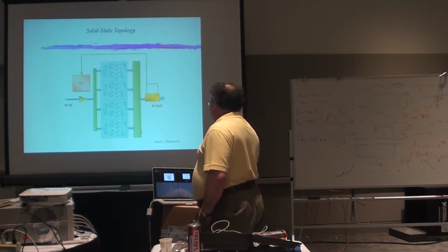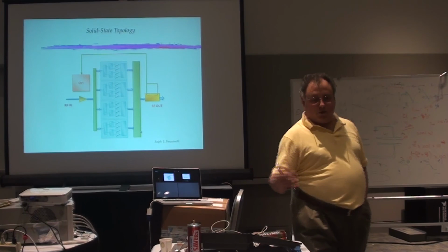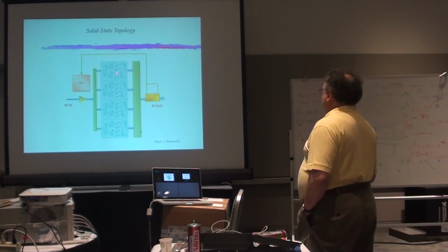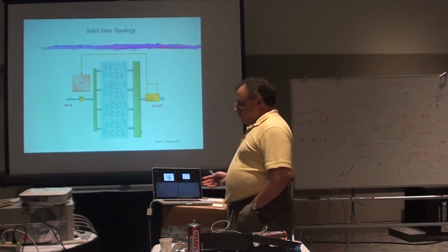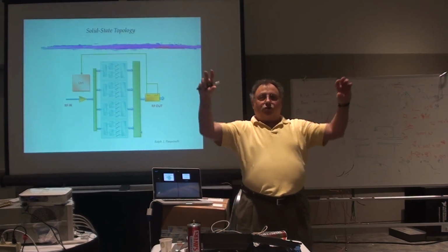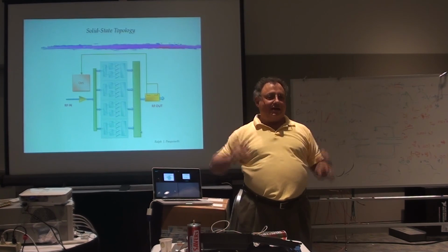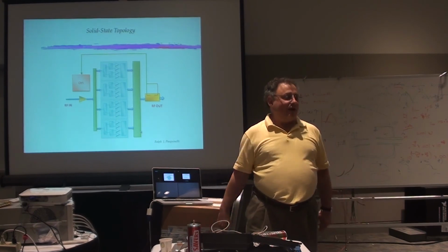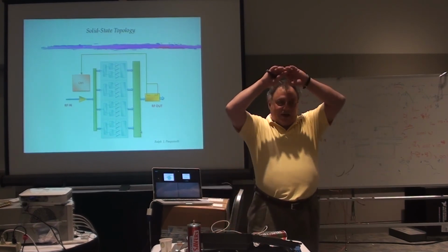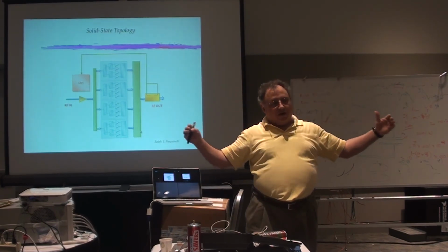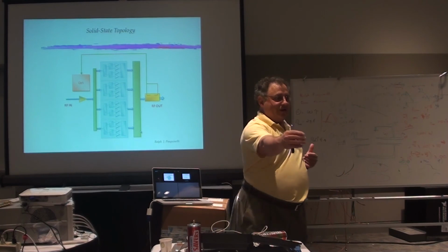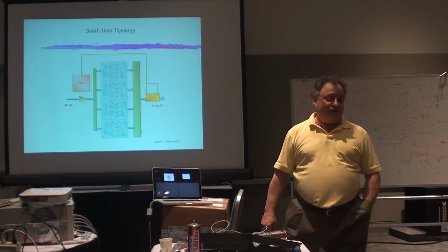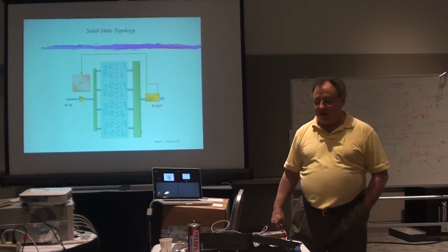Okay, then there's solid state topology, and we do have two 75 kilowatt amplifiers we just purchased. They arrived this past summer. But when you want to make a lot of watts, it takes a lot of transistors. The units we have have 16 drawers, each loaded with 8 transistors, so 128 transistors, each running at 600-and-something watts, all combined to make 75 kilowatts. This thing, I'll have to show a picture. This thing is 3 relay racks, but not just standard relay racks. So it's about 4 meters wide, 3 meters tall, and 1 meter deep. And it has power supplies and lots of stuff in it. It's pretty complicated. It's taken us months to get it to behave properly because it was a new product from the company that we bought it from.